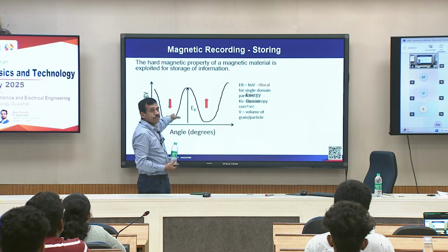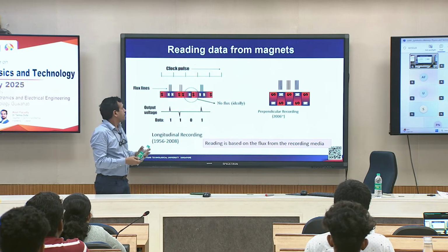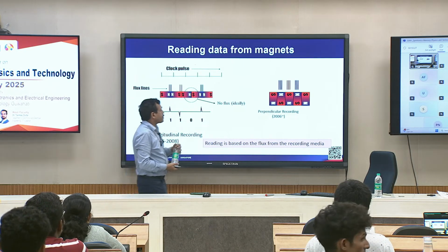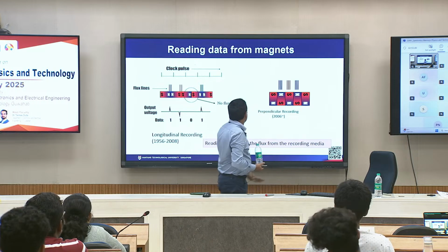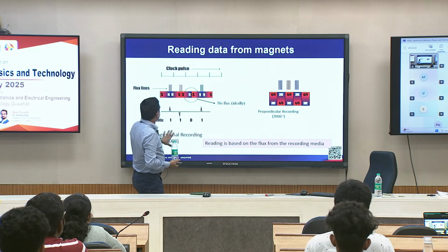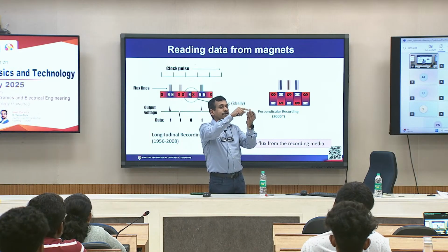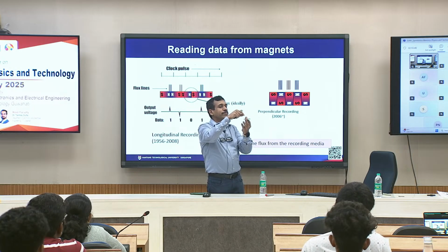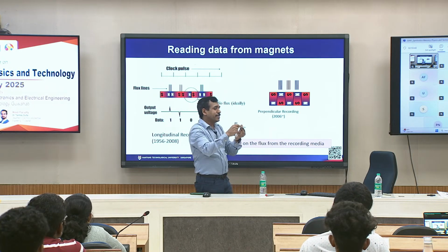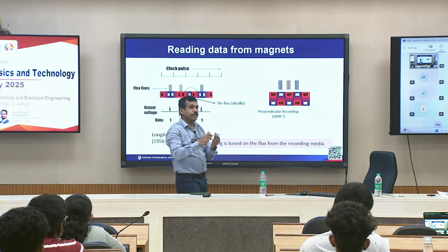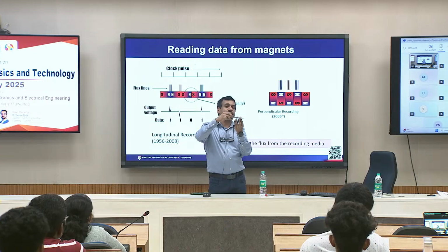You mean this drawing? The one before? Okay. You don't understand this one. Okay. So, in longitudinal magnetic recording, you have a disc, and on the disc you have a film. In the film you have grains. Those grains have an easy direction in the plane of the disc. So, you magnetize them pointing either in one direction or the other.